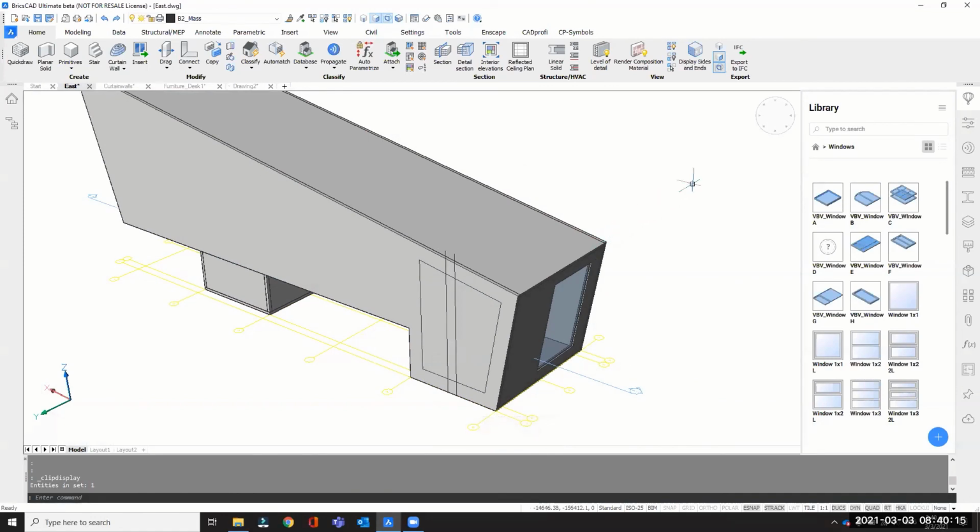So we have a command called BIM window create. It will create the window based on certain information or certain entities that you select. If you see on page 34, there are 3 types of input geometry for this. One will be a closed boundary on any solid face, one is a closed polyline, and another is a grid. So we'll see those 3 today. Let's first go into a solid polyline.